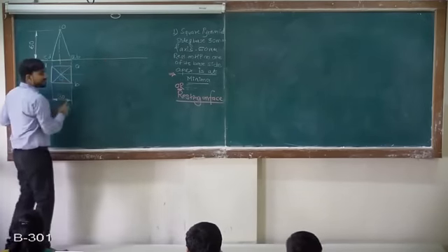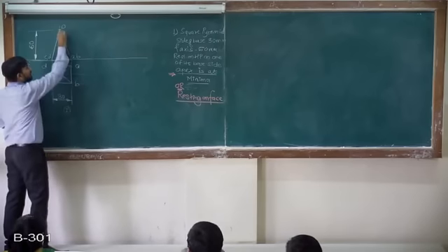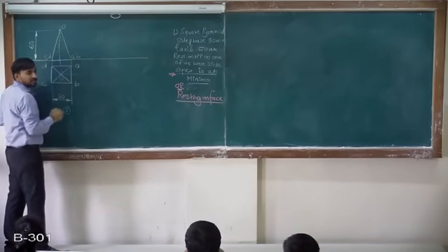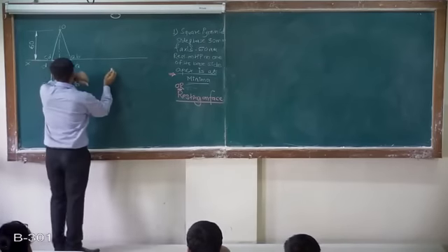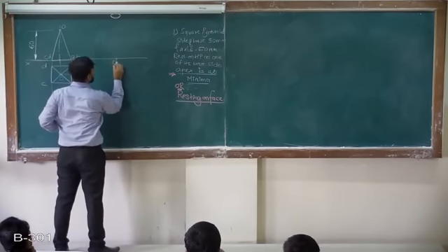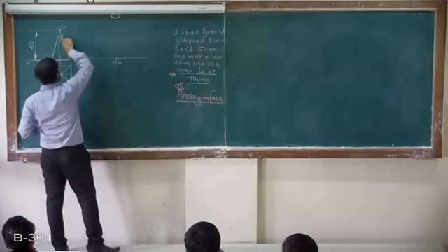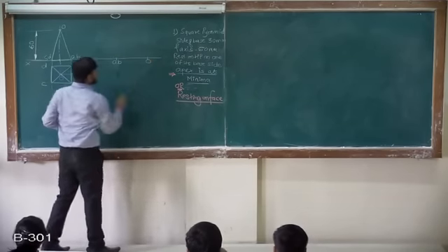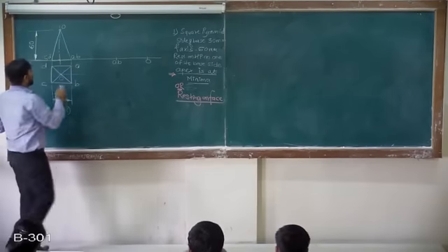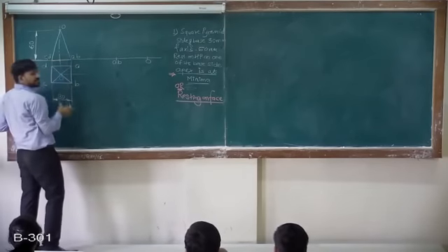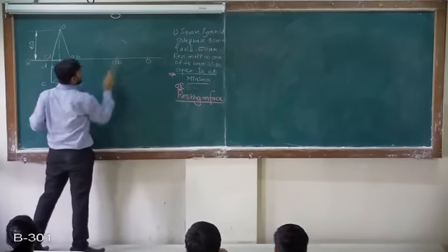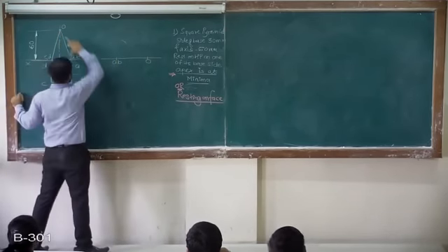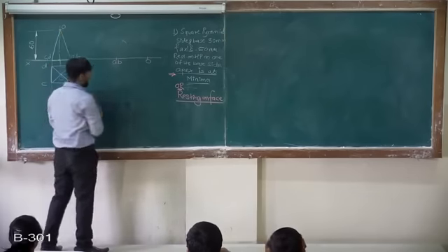This face is ABO. This is a triangular face. This is now resting on HP. So I will take this as AB. Take this length AB to O, mark from AB. Let's say this is a point. Now take the AB to CD distance, mark one arc somewhere here. Now take the AB to O distance, mark from O somewhere here.